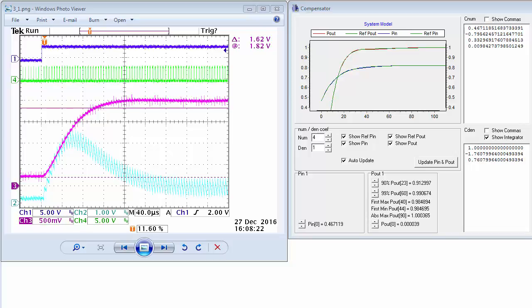Now we can see the overshoot is about 0.03%. This is about 1 ADC count on a 12-bit ADC converter. Realistically, we won't see this error. We should be quite satisfied using this compensator.